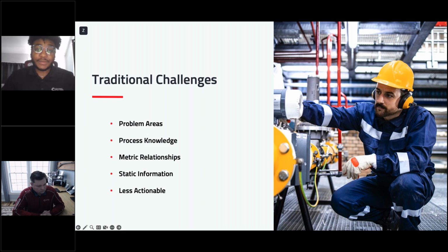And I would say possibly the biggest limitation is the requirement of significant process knowledge, right? CLPM is able to take all of the data that your process is spitting out and provide you with a ridiculous number of metrics that will inform you how it's performing, how it interacts with other control loops, but it can't tell you whether those metrics it's calculating are good or not, right?